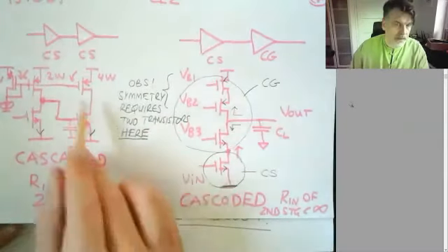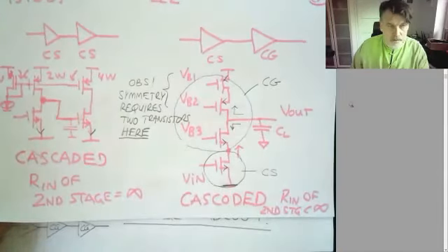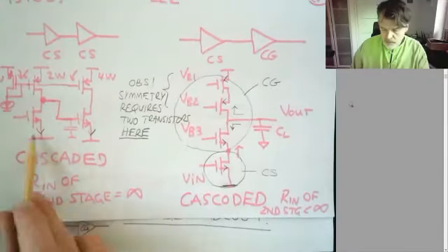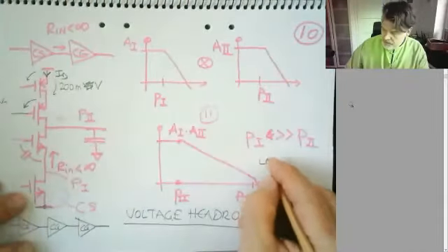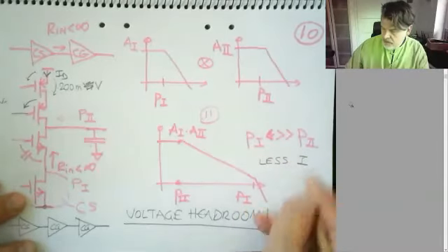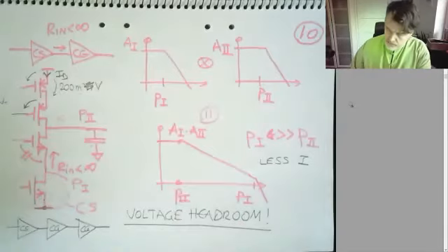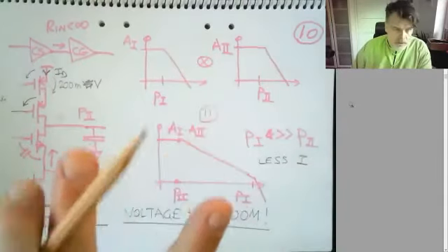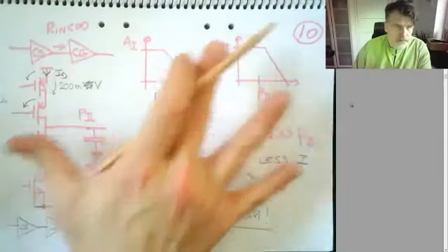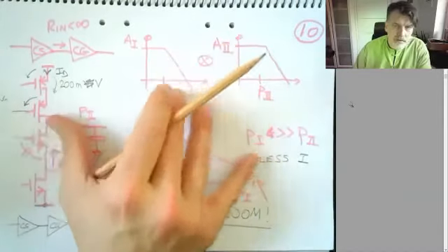And it might be that this requires a larger power consumption because we need more current to drive our circuitry. So less I, and the other ones are just vice versa then. So this sort of helps you when you design your operational amplifier.